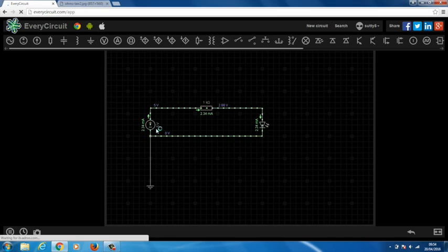So in order to limit the current to our LED, we need to keep 3 volts for our LED. So if we take away 3 volts from the 5 volt power source, we're left with 2 volts. And so this is where we will use Ohm's law, as we need to introduce a resistor to drop that additional 2 volts and limit the current for the LED. So now with that 2 volts we can calculate the resistor value we need in order to drop those 2 volts and supply the LED with 20 milliamps.